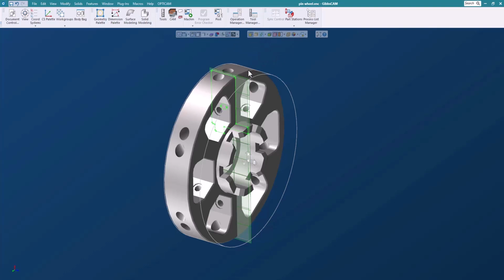Now, a couple things we can do here. I want to create a solid, so I'm going to select the profile here. I'm going to extract geometry, create a solid, offset it, and make it stock so that we can machine. Then we're going to come back and machine this using the profiler, not geometry. Okay, so let's go ahead and do that.